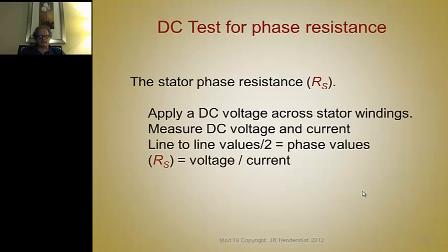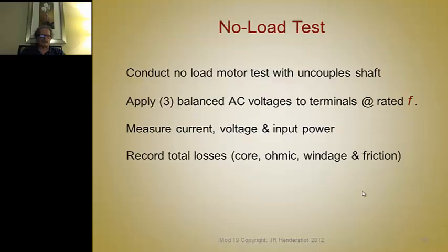The stator phase resistance is measured by applying a DC voltage across the stator windings, measuring the DC voltage and current, and then calculating the resistance from that. You can use a very accurate resistance bridge to measure that as well, of course.